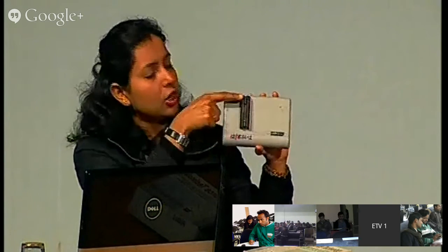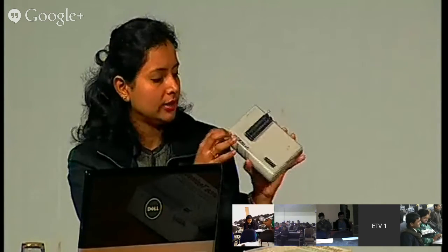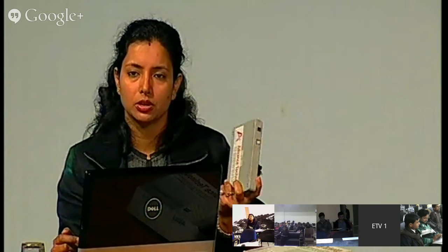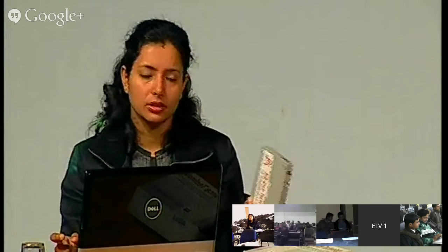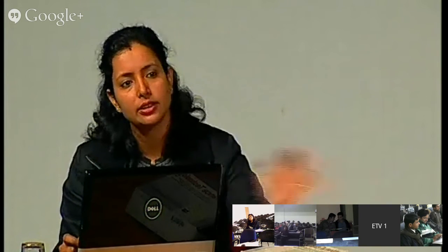So this is a lock. You simply insert your controller into this, you have to lock it first, and then through this programming cable you simply download the hex file into this. So this is one kind of burning of the program into the microcontroller. But in this case, every time you have to take your controller out of your application, put it here, burn it, and then put it again into your board.